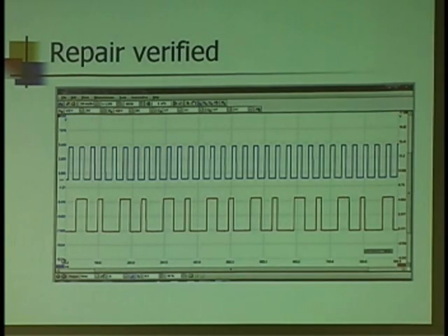If you have a sensor that you want to read and get a good, accurate pattern on your screen, if it's a floating ground, you must reference your scope to the same ground. You'll get the same shape if you reference it to chassis ground, but you won't get the same amplitude. And that can make a difference.